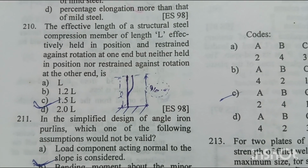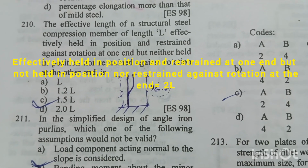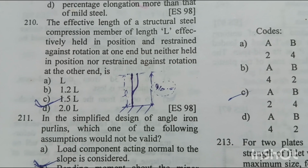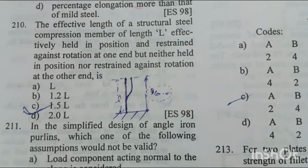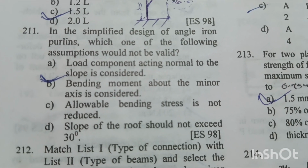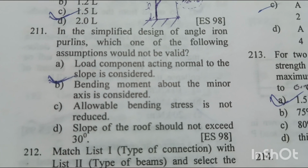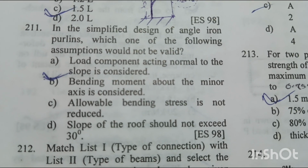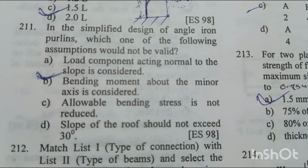Question number 210. The effective length of a structural steel compression member of length L effectively held in position and restrained against rotation at one end but neither held in position nor restrained against rotation at the other end is 2L. Option D is the right answer. Question number 211. In a simplified design of angle iron purlins, which one of the following assumptions would not be valid? Option B will not be valid. Bending moment about the minor axis is considered. No, bending moment about the major axis is considered.